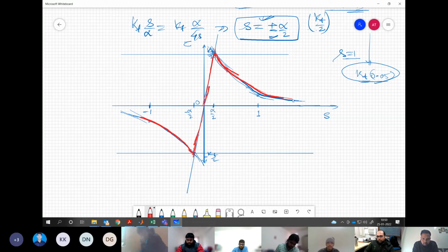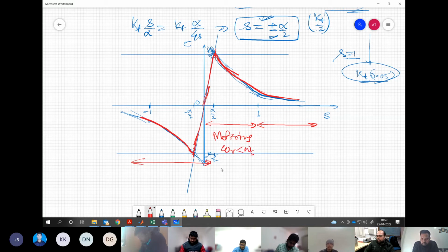Now the different modes what we are getting for the induction motor is like 3 different modes of operation we are getting over here. Whenever the slip is between 0 and 1, this is basically the motoring mode. And this is where we say that our rotor speed is less than synchronous speed. Then whenever we cross 1, basically this is the plugging operation.